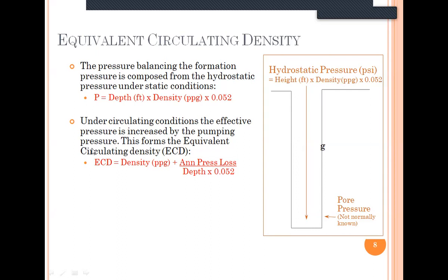And the ECD is very important while drilling. You remember yesterday when we talked about the functions of drilling fluid, one of the functions is to provide information from the downhole tools. One of these tools is the PWD, the pressure while drilling tool, and it is mainly concerned with measuring pressure while drilling and ECD.